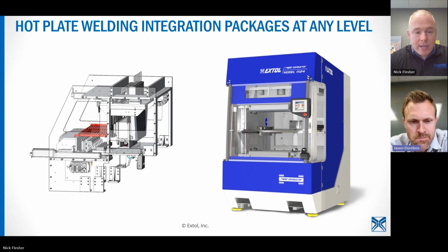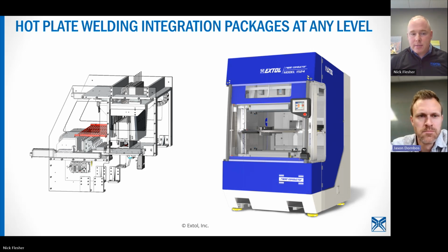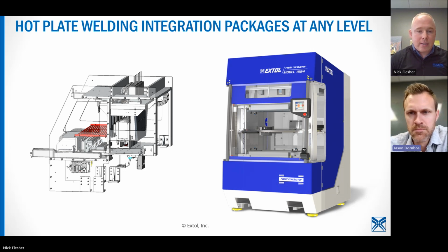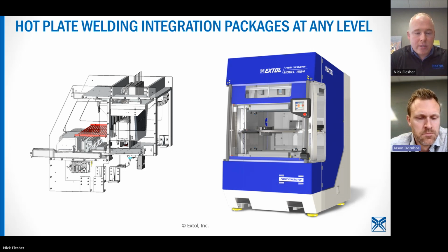Oftentimes with hot plate welding, if you can commonize tools, that's great. The hot plate welding process is really beneficial for melting away any imperfections or variations that you have. You can't really do that with non-contact. So this is one solution that we customized. We did run this off at our facility before we shipped it for factory acceptance.